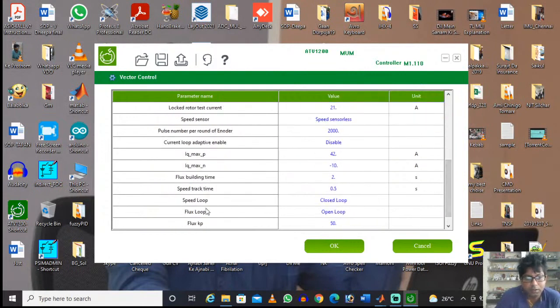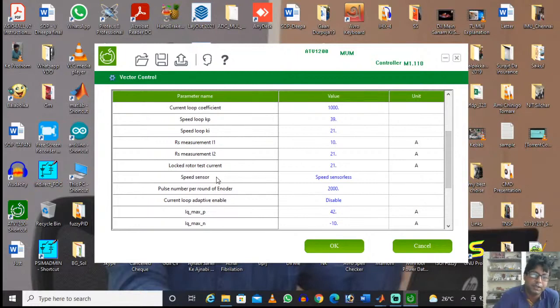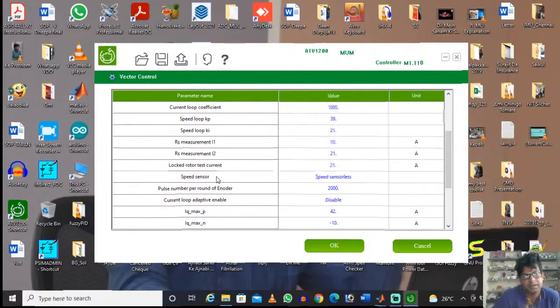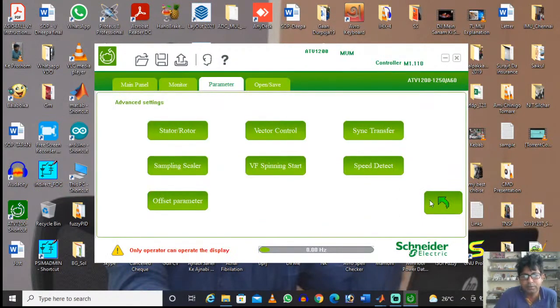This is the torque loop kp and ki, but in this drive the flux loop, as it is an internal loop, is estimated automatically. Based on all your parameters, the drive will calculate the kp and ki. You don't have access to that. Some company may provide it, and then you can set it, but here you cannot. After all these things, if you start the machine, it will operate. I have given just one glimpse so that you can conceptualize why you have learned all these things, because this is required in the practical field when you go to work.